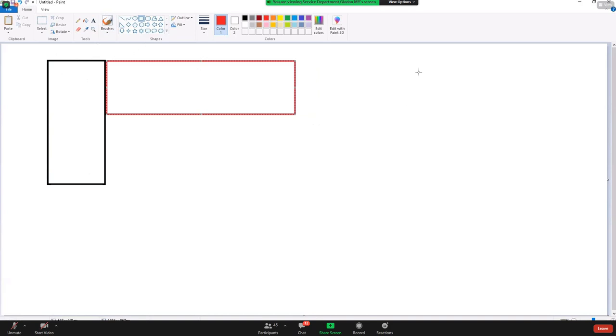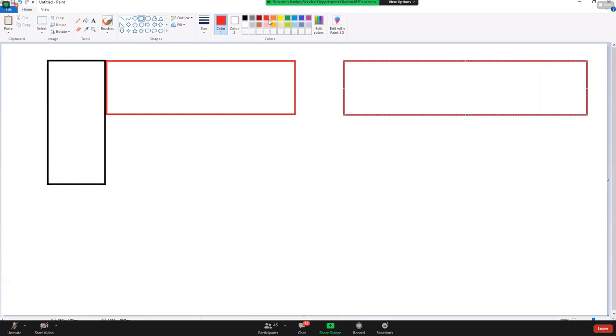For frame beam, the slab will take full extent, and the frame beam concrete will take only until beneath the slab. So this is the difference between these two. It depends. In this training, I'm going to use beam only. The modeling part will be similar.